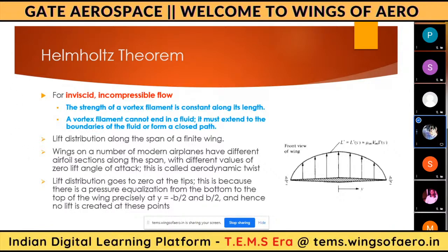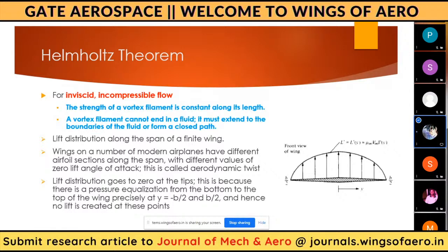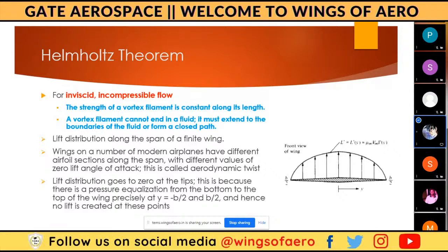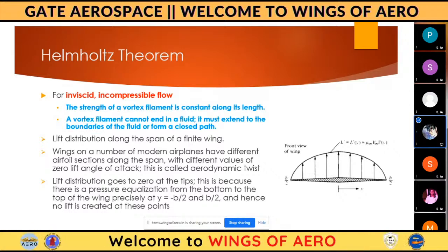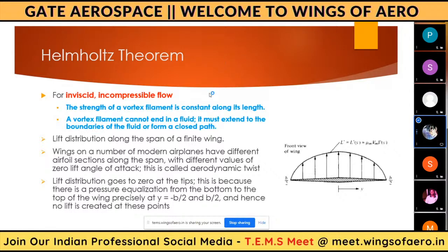After the trailing edge section, we will have an extended control volume over that. Why are we doing that? We will be meshing the aerofoil into so many parts, that means elements and nodes. Most researchers, in the trailing edge region and somewhat extended backwards, will give a fine mesh.